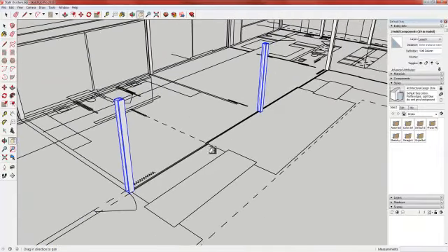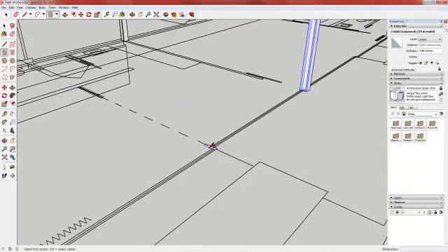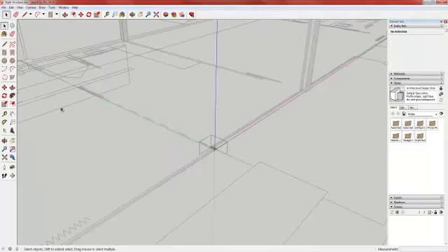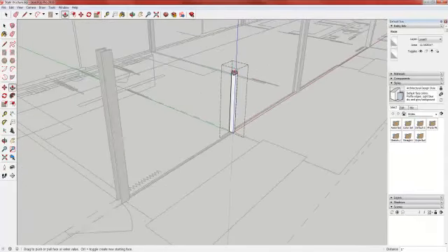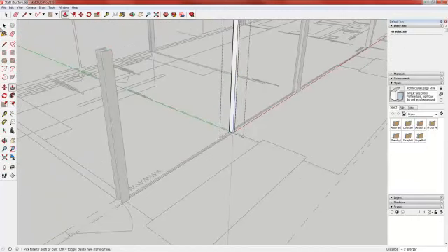Excellent. And we'll double check and see what's going on here, but I have a feeling we have a couple other little framing members that are helping support these spans of glass. Those are pretty big spans of glass. So we'll add those. Let's go ahead and add those in now so we don't skip a step. And again, with these smaller objects, I'm going to just make them a group. And then we'll push the group up to match the column heights. And if I hover over the column extrusion, I can just hover next to the column and I should be set.